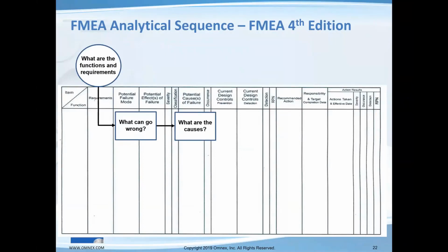In the 4th edition, the what can go wrong, of course, was at the focus level. We focused on the causes of the current design. That's what the 4th edition did. We didn't immediately go to the lower level and say, yep, all of this is your failure, supplier, or inside the company supplier. We said, what can go wrong in the current design?